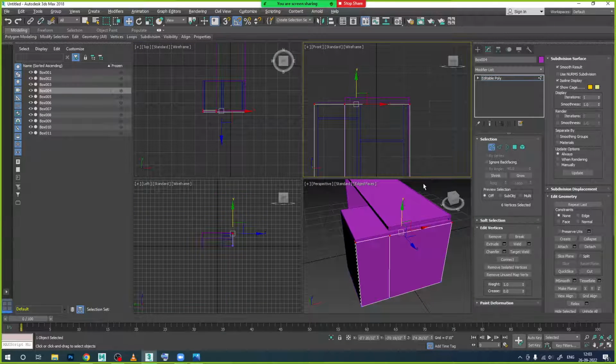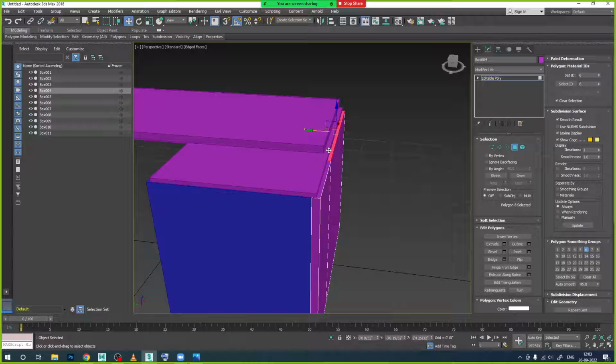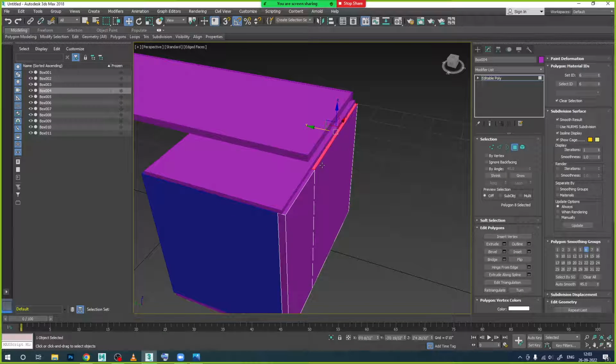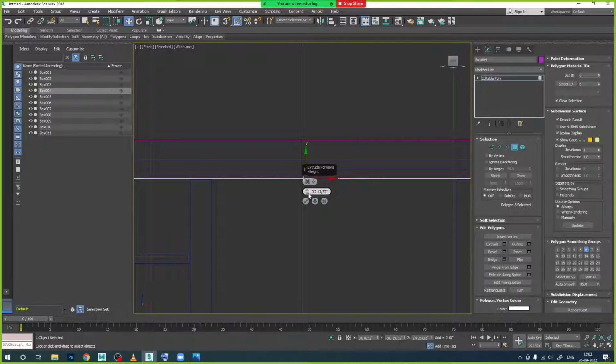Okay, now zoom again on this area. Now we want only this edge to be taken on this one. So select this one, go to the faces, select this only face on this area, and this also we need to cover. So use extrude option in this one, select this face only, use extrude option, and what we do, we just drag this one down to have a plane surface on this area. Now if you want to see clearly on this one, you can go to the front side view, reduce and see the size in this one. Once it is done, accept it.